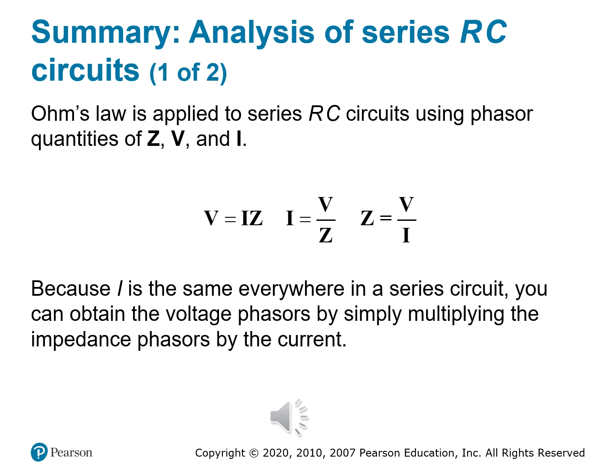And Z is equal to V divided by I, where impedance is voltage over current. This isn't new. It's just Ohm's law upgraded, Ohm's law 2.0, to work with complex numbers and phase angles. And why use phasor form?